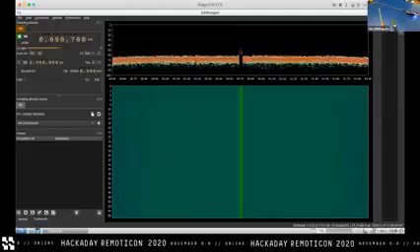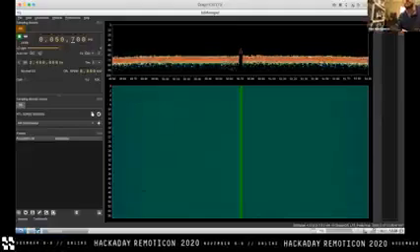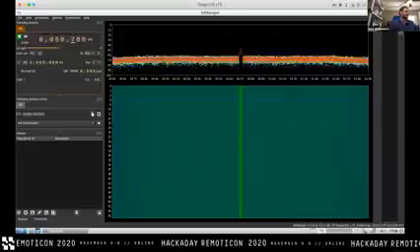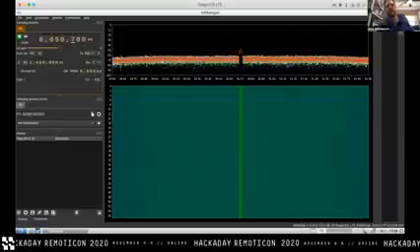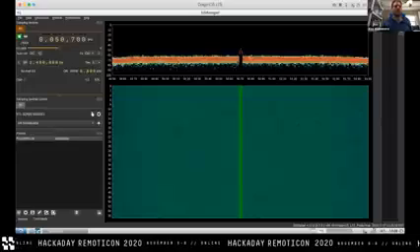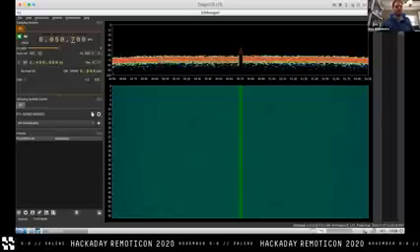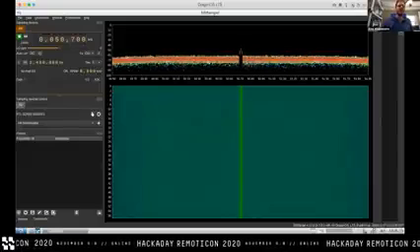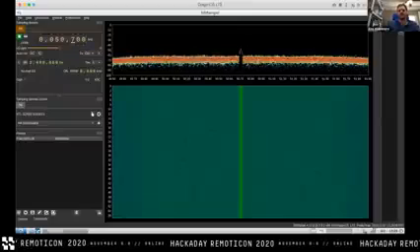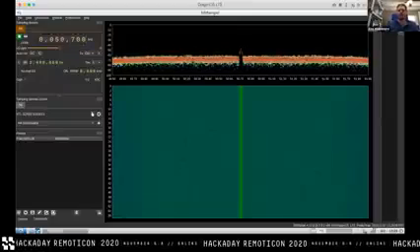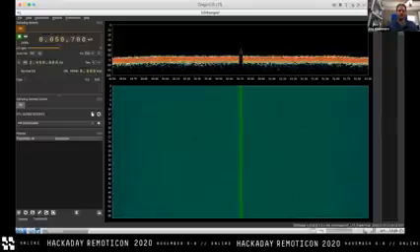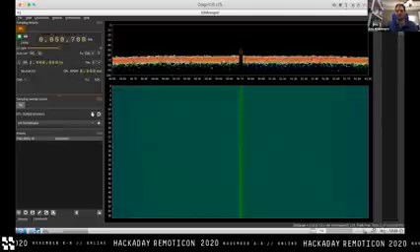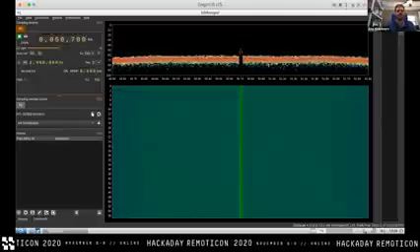And I guess this would be a good time to interject with the merits of different SDRs. So we've been using this RTL SDR this entire time, and really the only reason we've been doing that is because it's super cheap. It's rarely the best SDR for the job, it's just super cheap, so if you can get away with it, you ought to, because then you don't have to go spend money. The key figures of merit that are relevant for any of these SDRs, there are basically two that matter most, one of which is real-time bandwidth, and one of which is total tuning range.